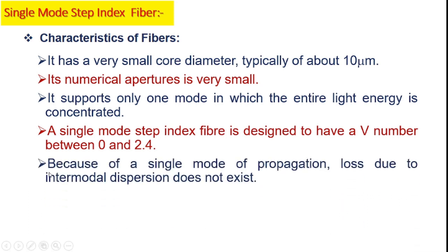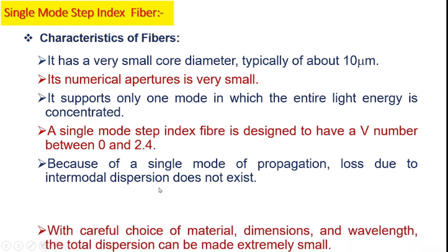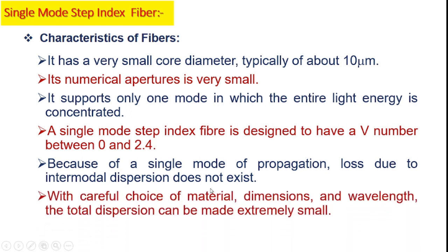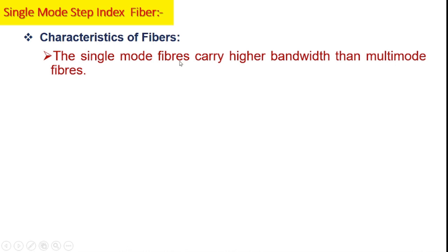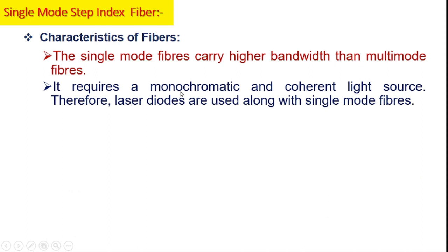Because of a single mode of propagation, loss due to intermodal dispersion does not exist. With careful choice of material, dimensions and wavelength, the total dispersion can be made extremely small. The attenuation is least. The single mode fibers carry higher bandwidth than multimode fibers. It requires a monochromatic and coherent light source. Therefore, laser diodes are used along with single mode fibers.